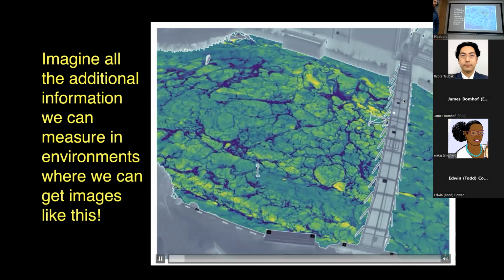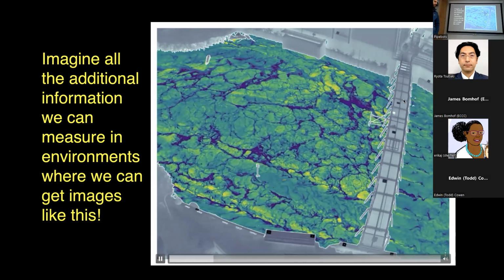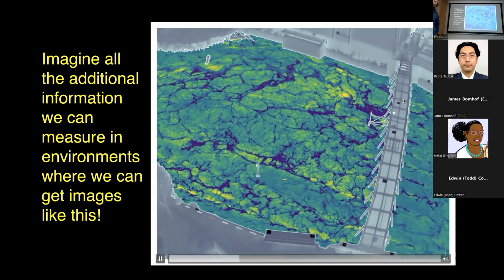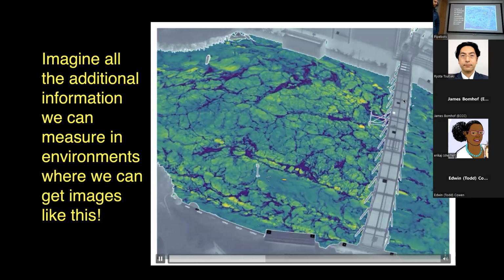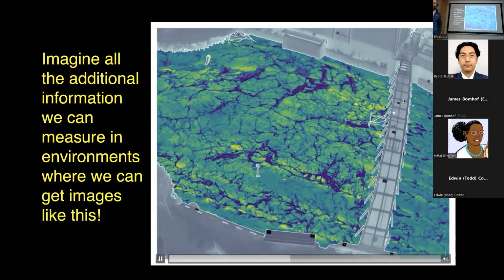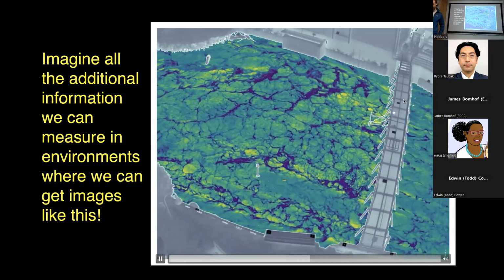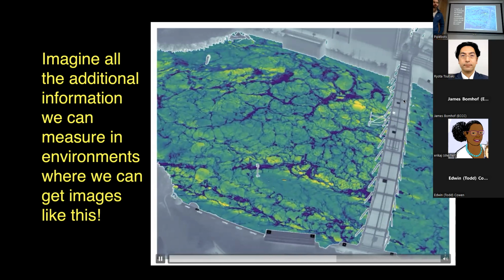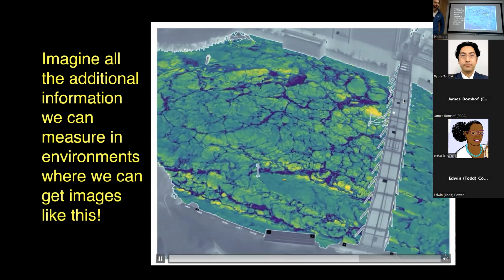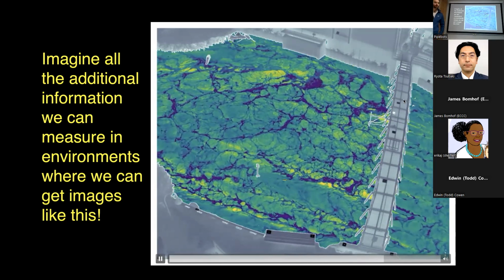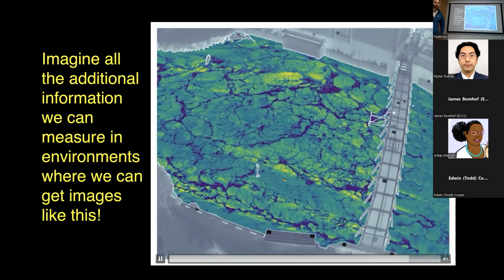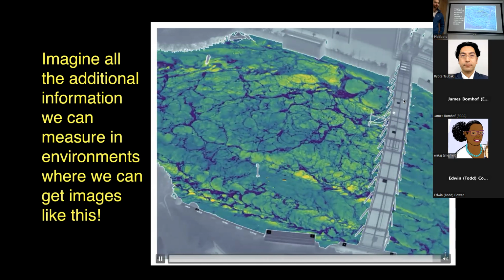And the question is, can we understand that physics enough, what the aeration is, enough to understand how to correct for the fact that there's a lot of air there, and use that information then to perhaps even tell us how much air is there, what is the void fraction, to accurately estimate all the things we need now, including Q and how much water is actually underneath that aerated free surface.